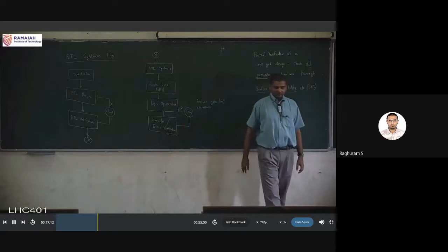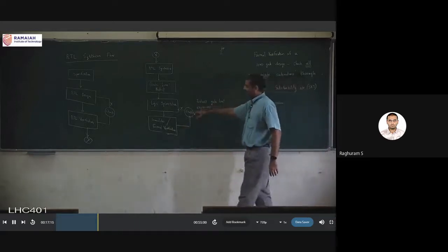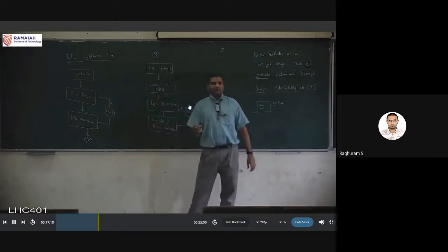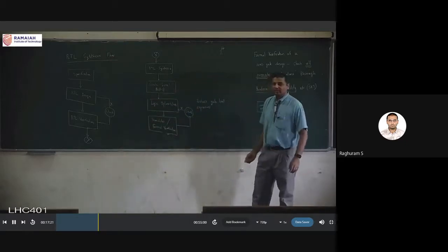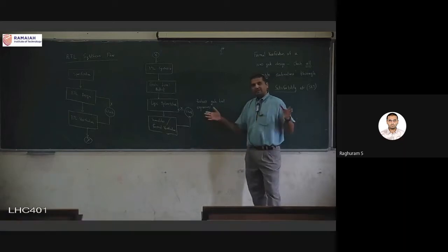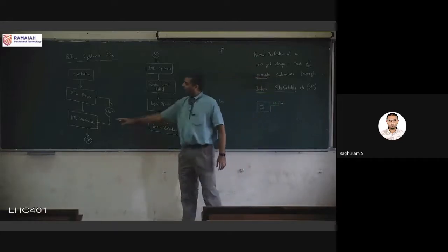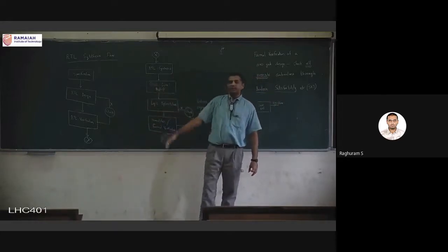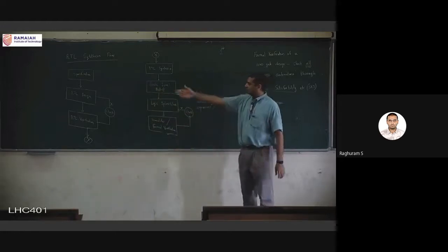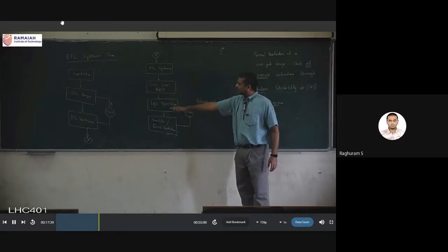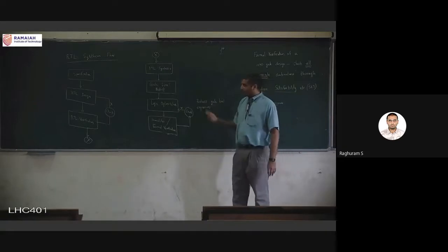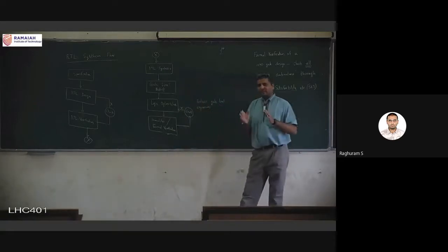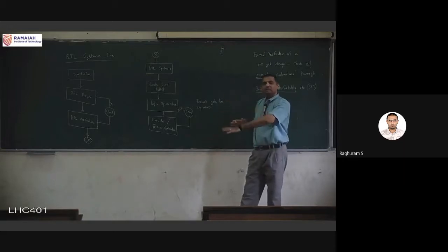And another interesting aspect of this whole VLSI design, we see these checks a lot, right? And I said that the checks are when some error is happening, so it might require some manual intervention. In the overall VLSI design flow, okay, 70% of the time is going for the verification steps. So if you see, after every design step, there is a verification step: RTL design, RTL verification, gate level netlist, logic optimization, then simulator or formal verification. Similarly, in every step, there will be a verification step. So in the overall design flow, 70% of my time is going for verification. Only 30% is the actual design step.